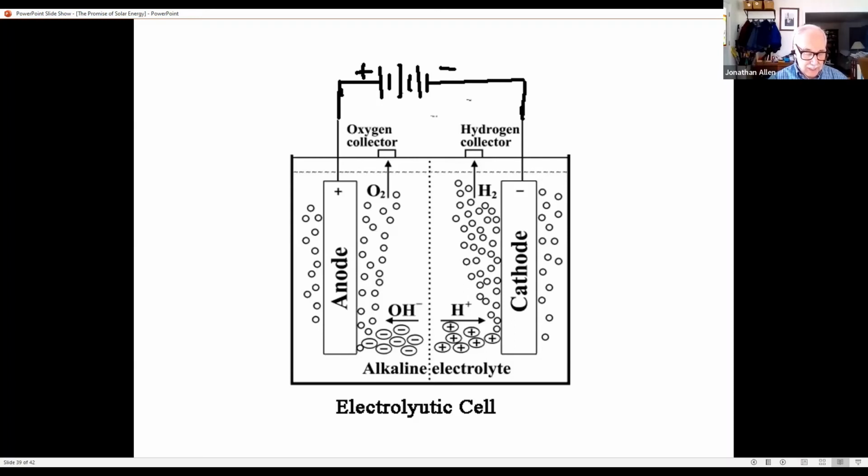Hydrogen has even more watt hours per kilogram than do the petroleum fuels, even if you have to include the weight of the pressure tank for compressed hydrogen, or a cryo vessel for liquid hydrogen. Hydrogen's energy density is, of course, dozens of times that of the best lithium-ion batteries. And interestingly, almost any heat engine that can run on hydrocarbons can also run on hydrogen. In fact, for the gasoline engine, it has an equivalent octane of better than 100.